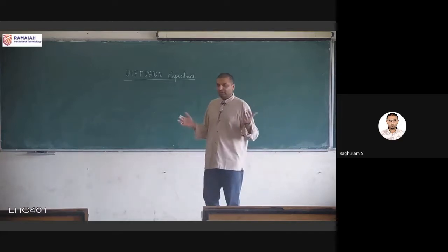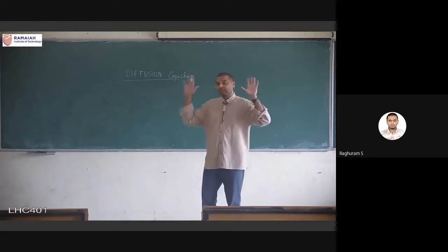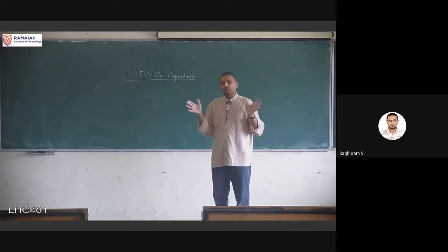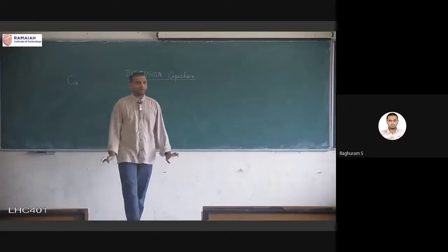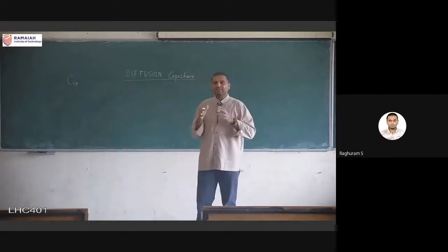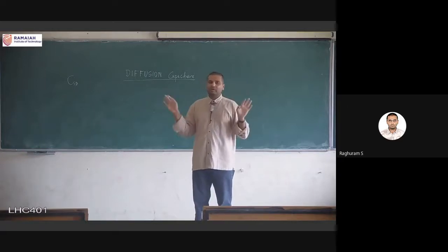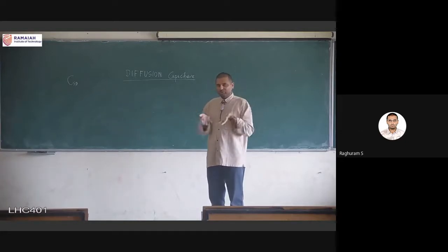So this is the capacitance not between those two. There is no direct contact between the source and the drain. The source and drain separation is somewhat large, so there is no capacitance called, for example, C source-drain. It's not there. The separation is so large that in A epsilon naught by D, the D is very high, so C becomes very small, close to zero, negligible, almost no interaction between the source and drain through the substrate.